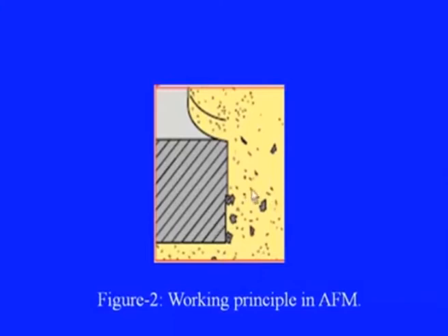So, we can think of this as the workpiece surface to be finished, where roughness is to be removed. Now, these are the abrasive particles that come in contact with the surface of interest and cause micro cutting on the asperities of this surface and remove some material in the form of small chips. We can think of small chips being produced as a result of this AFM.